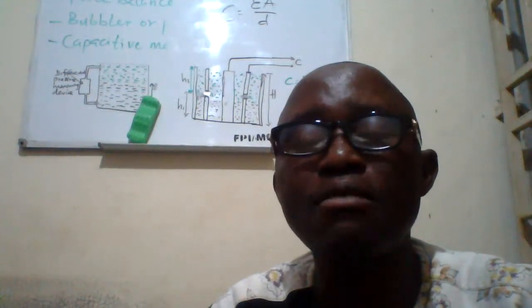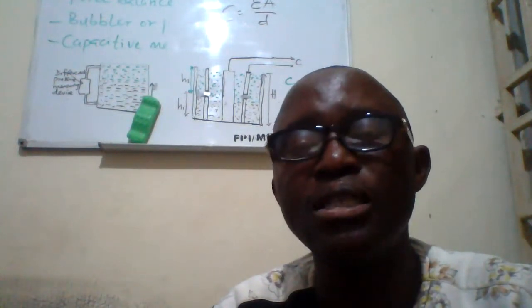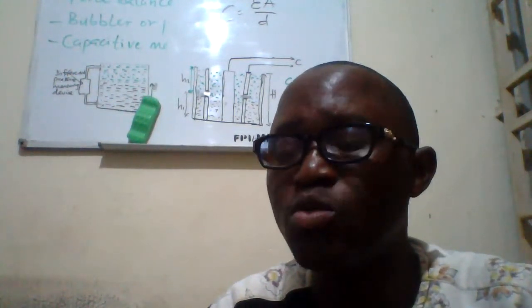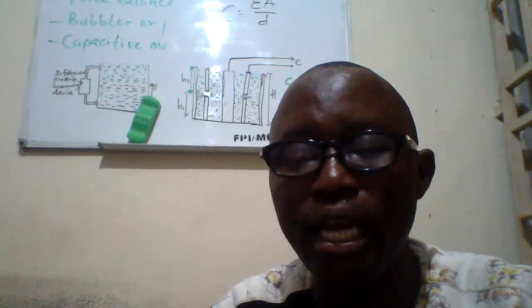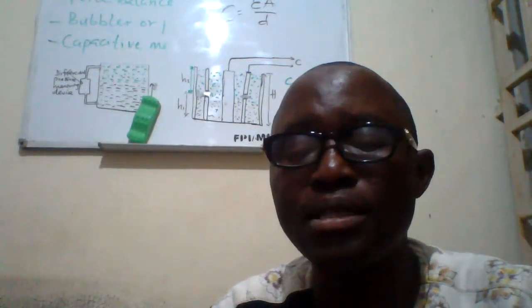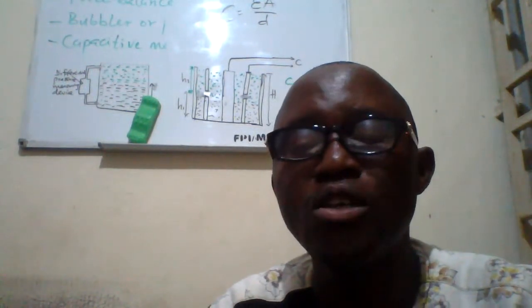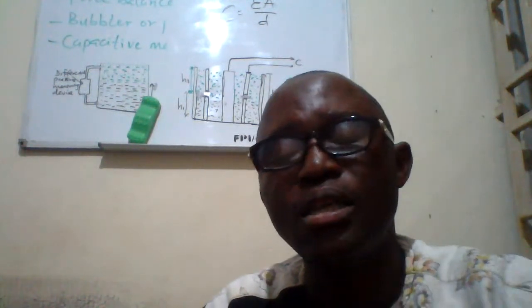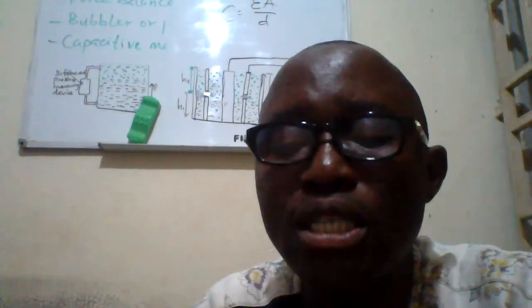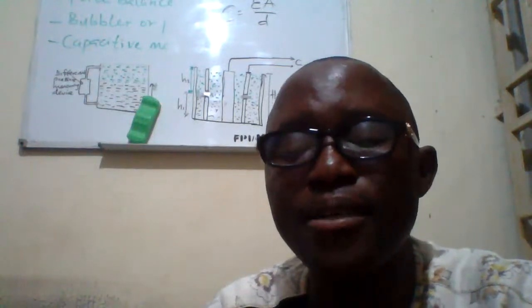Now, the capacitance developed will determine the height of the liquid, because when you look at the formula given, you see that the height of the liquid HL is among the parameters in the formula, so that at the end of the day, someone can calculate or determine the height in the tank.